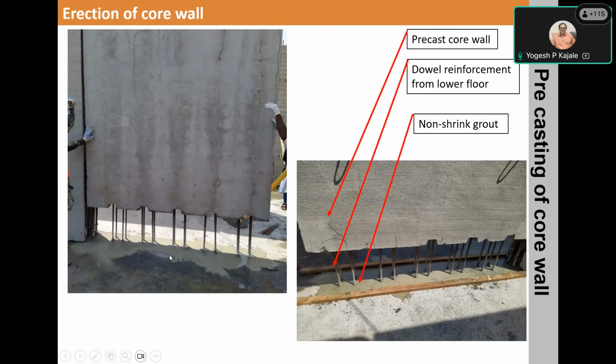Then the lower story reinforcement coming from the lower story shear walls gets anchored into the upper story shear wall into the core, and then the concreting happens within the core. So when the walls are installed in the permanent building, there are no hollow cores left inside the shear walls. All the cores are filled with concrete.